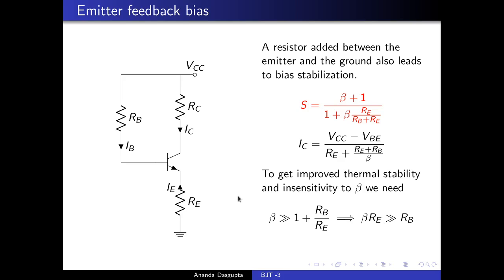So for this circuit to be a good circuit, RB cannot be too big, because if RB is too big, then this factor really ends up being rather small here. So the improvement on S is rather small. Also, if RB is very big, then this factor will not really be small compared to this beta independent factor, and so you'll have to take the beta dependence into account.